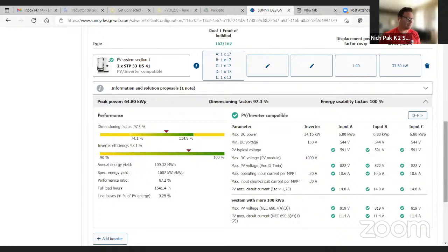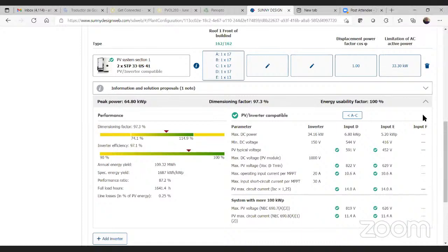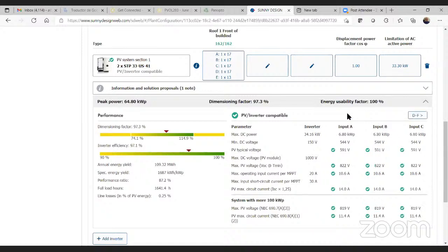We've been asked by a multitude of installation companies, as modules get bigger and bigger and start to exceed 2 meters, it usually is these 1500 volt modules that you were just talking about that we're seeing installed in more and more field uses. And just to be very clear, if anybody is having any confusion, the DC voltage limit on the Core 1 is 1000 volts. So you can't string past that, but a module that is certified to 1500 volts can certainly be used as long as the string design does not result in higher than 1000 volts being seen at the inverter terminals.